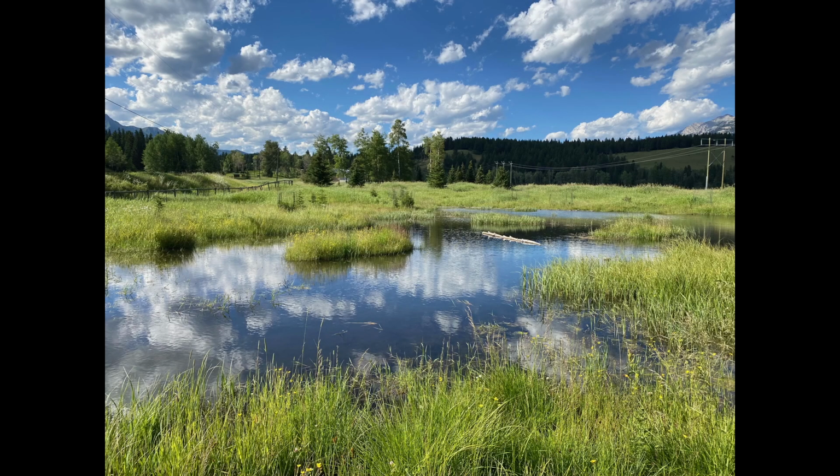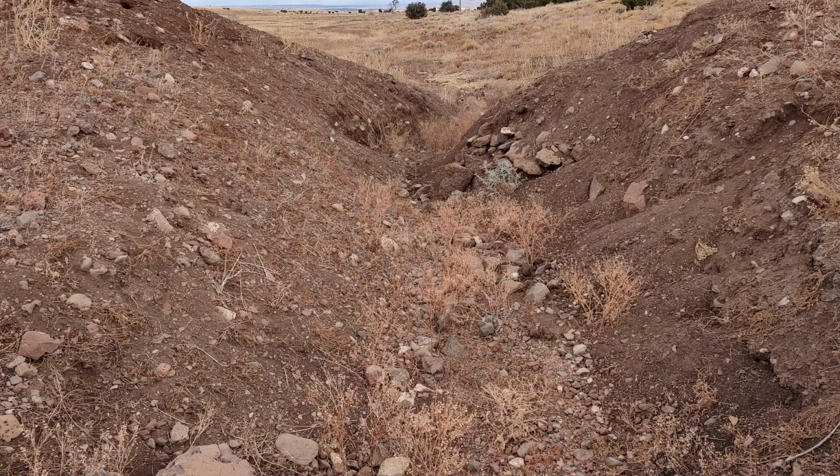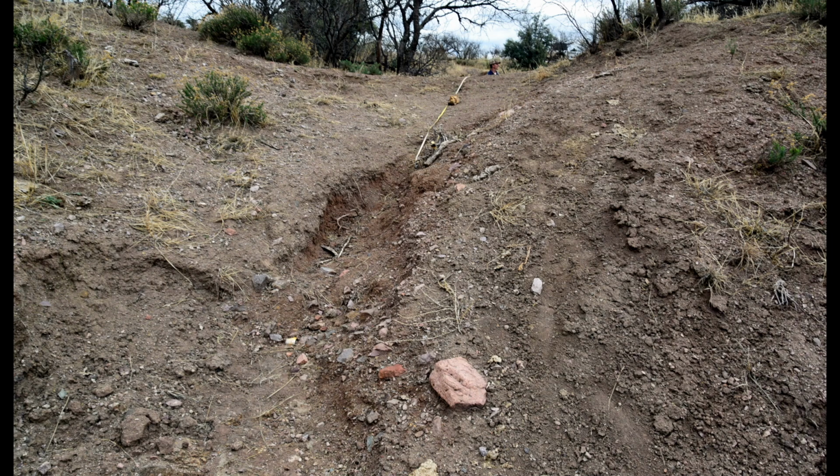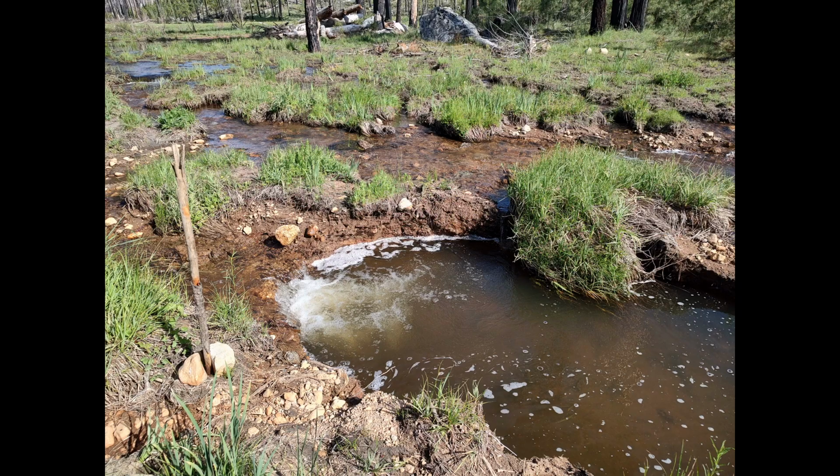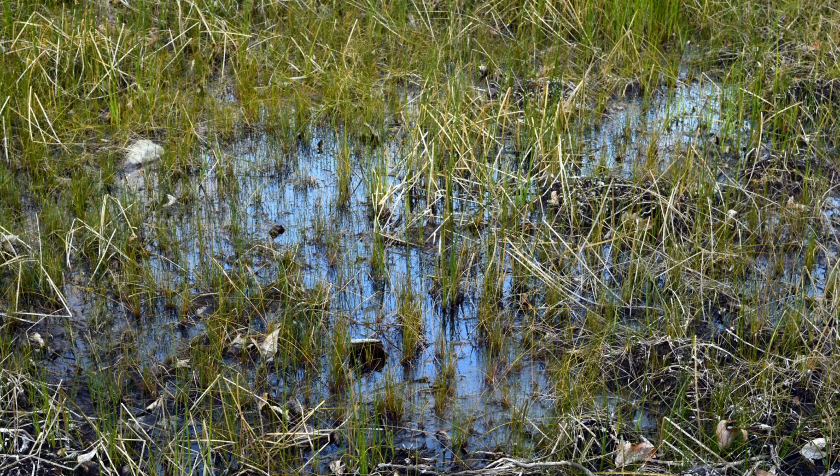In summary, it's important to remember that every wetland needs a spillway, whether the wetland is natural or constructed. A poorly designed and constructed spillway will result in the eventual destruction of a wetland. In a poorly built spillway, head cuts advance up the spillway and they will drain the wetland basin. It's entirely possible to create a spillway that will also become a wet meadow wetland.